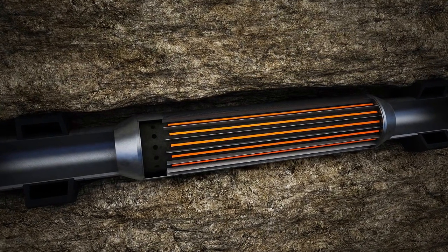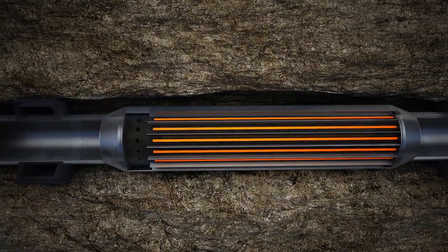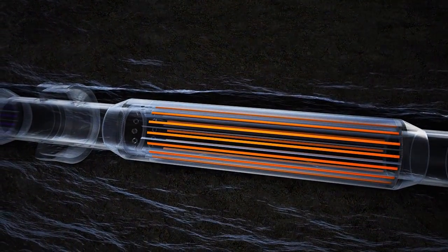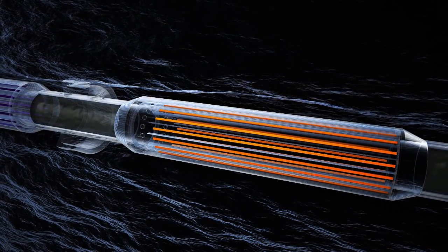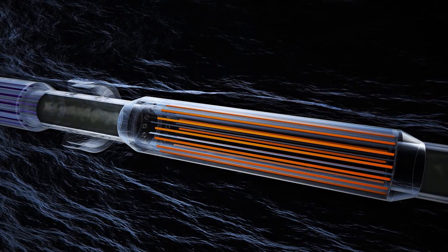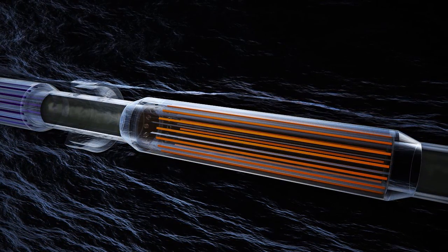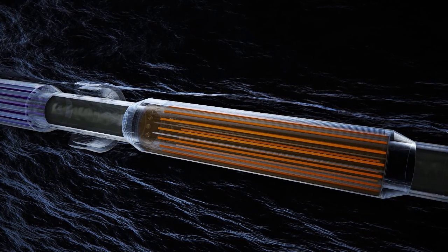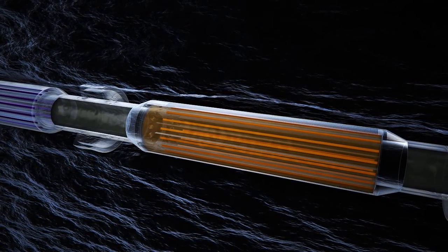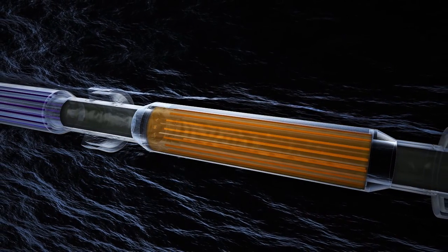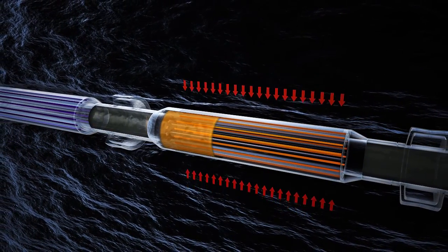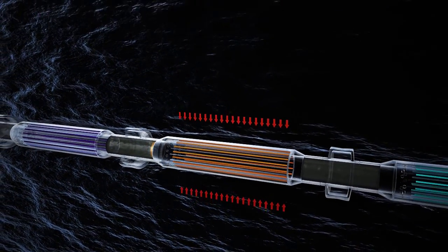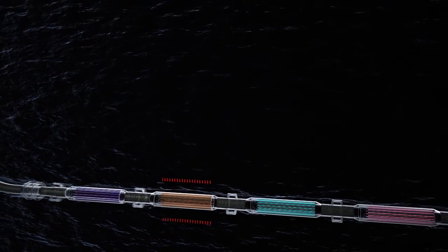Each zone contains material that releases a unique chemical signature to either water or oil, which is referred to as an intelligent tracer system. This shows the release of the tracer begins when the rods come in contact with oil. The release rate is constant, so when the well is static, the tracer builds up in the fluid surrounding the RESMAN tracer system. When the well is turned on, the fluid from the reservoir flushes the oil with the high tracer concentration from around the rods.